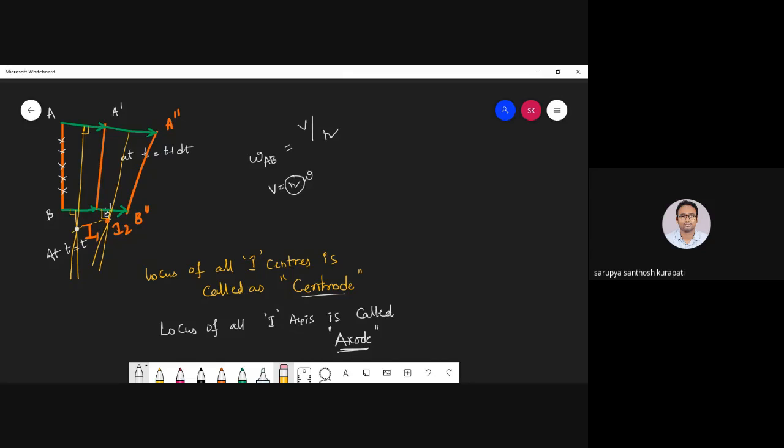Here I can name them C, D, E, F, G. You can find the velocity of point C, velocity of D, F, G, whatever it may be. But what about the radius r? If you want to find the velocity of point C, C becomes your reference, so the distance from C to I is what you need to measure. So velocity of C is equal to r, which is nothing but the radius.